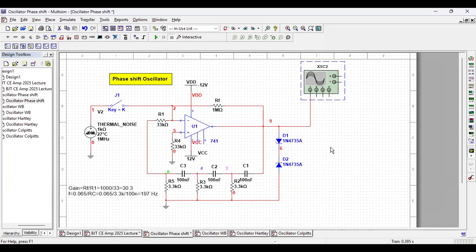That is because, if you go to another practical aspect, we have seen that an oscillator has a gain infinity. So it has an output when there is no input. But think of the very initial instant, very initial first microsecond after switch on. If there is no input, how can there be any output?